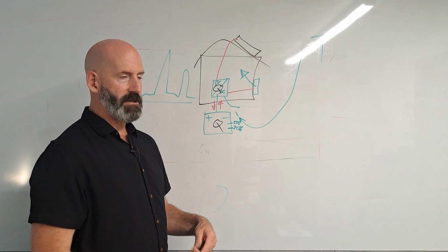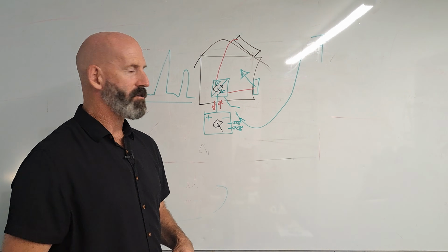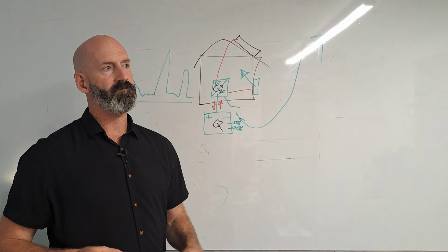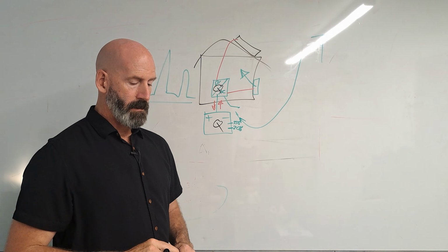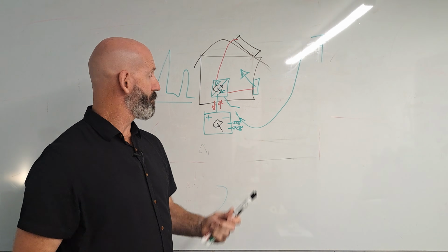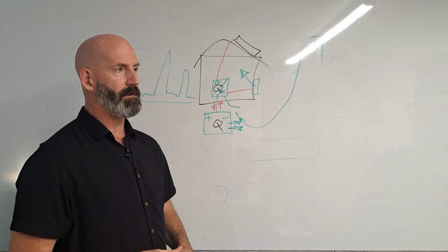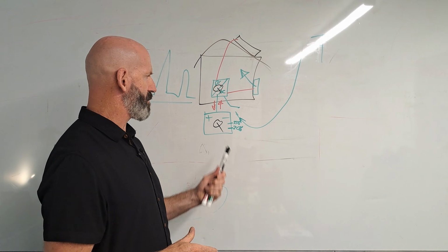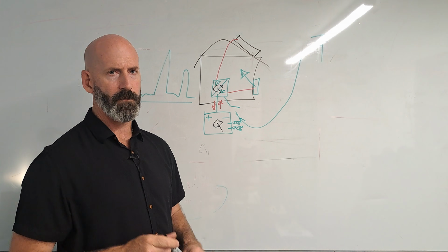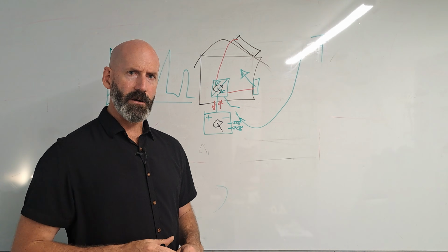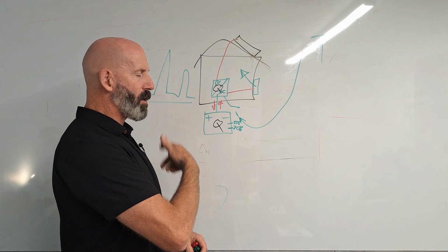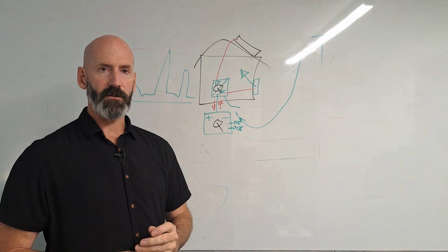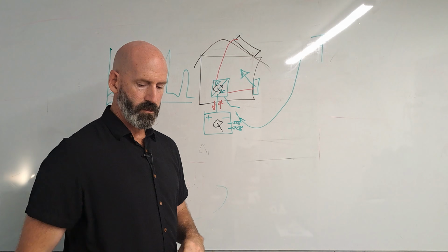If you never draw more than a kilowatt, those batteries will probably last you okay. But you're buying a 40 kilowatt hour battery bank so that you never draw more than 1 kilowatt off it. Kind of seems like massive overkill just to make sure you don't damage your equipment. If you start drawing big spike currents out of them, you'll find that cheap gear just won't last.